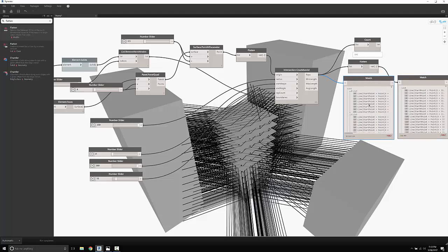So what we've got right now is a list of lists that have the number of lines, the actual lines. It's containing all the lines that come from a given point. If I select one of these, one of those somewhere down in there is blue. When I use a typical flatten, I'm going to get this giant list of 1082 lines without any structure. That's not what I want either.